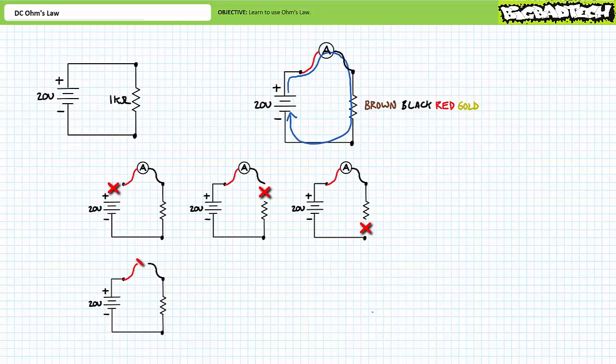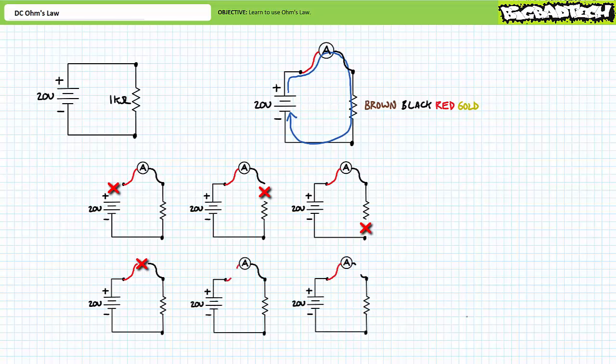In the event of a ruptured fuse, the ammeter itself prevents completion of the circuit and thus no current flows. Additionally, consider the consequence of damaged test leads or test leads that are not properly inserted that prevent completion of the circuit. In summary, if you observe no current flow, you are definitely dealing with an open.